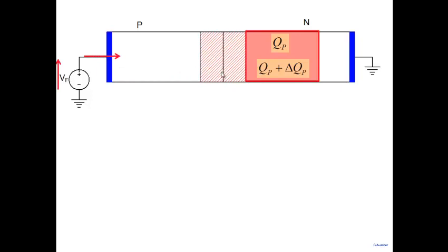But along with that, remember this whole region is neutral. So what has happened? Excess electrons have also increased. Where have they come from? They have come from here. Right? So the region is neutral, but I have excess holes here, so a current has to come and supply it. I have excess electrons here, and the current has to supply it. So from an external circuit, what does it look like? It looks like a capacitance. I have to supply positive charge from one terminal and negative charge from another terminal. Right? So it's just like a capacitance.